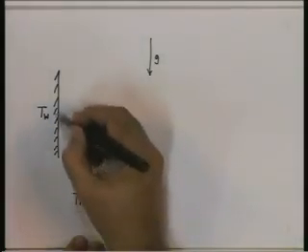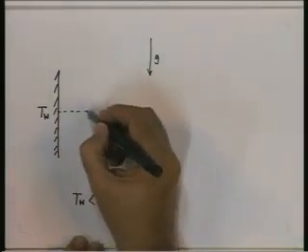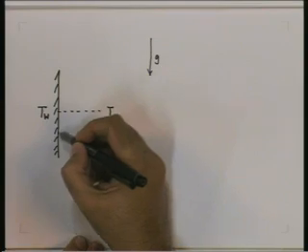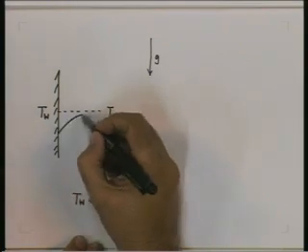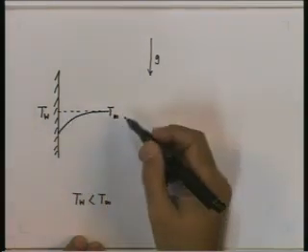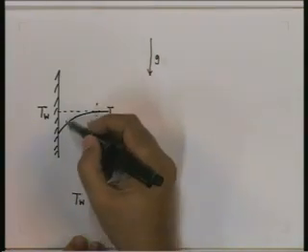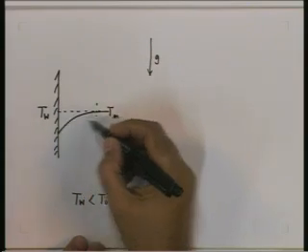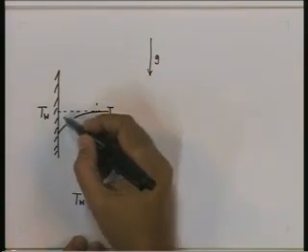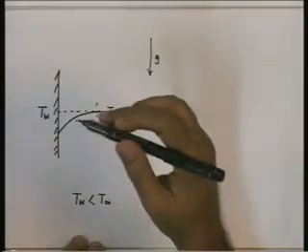Now what happens? The wall temperature is lower, some layers near the wall cool down, there will be a thermal boundary layer, and because of this lower temperature, the density here will be higher, the fluid will tend to sink because of higher density. The net effect of buoyancy would be to move denser fluid layers downwards.